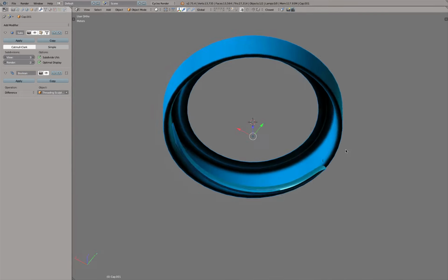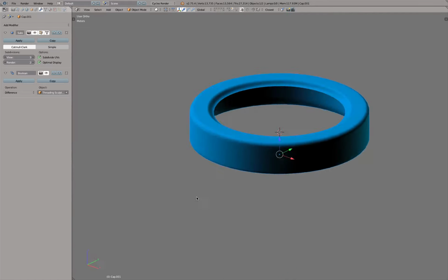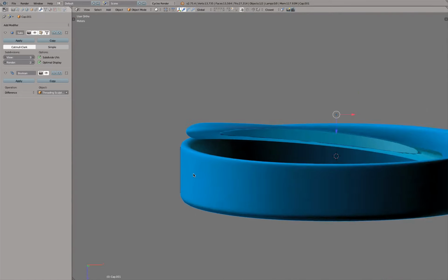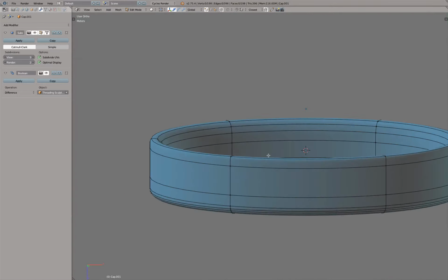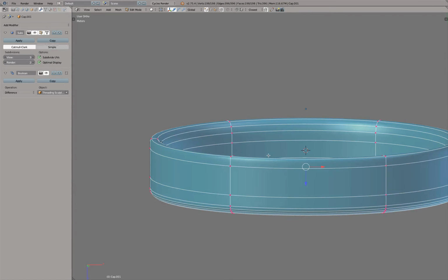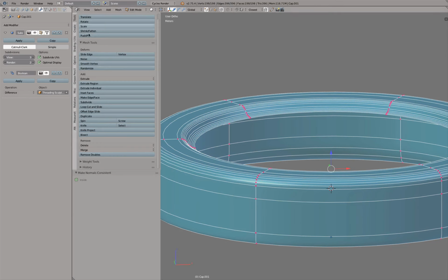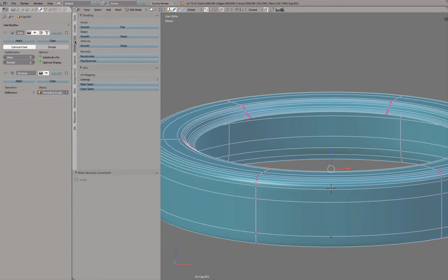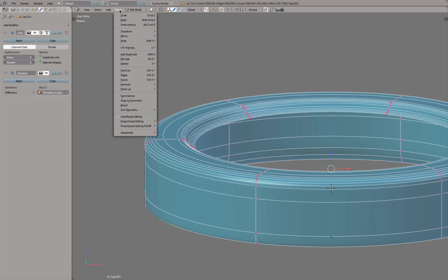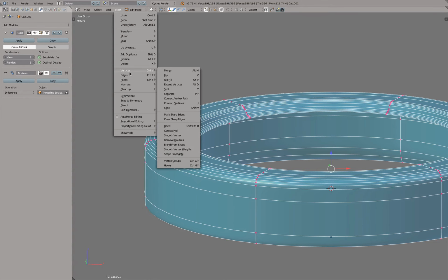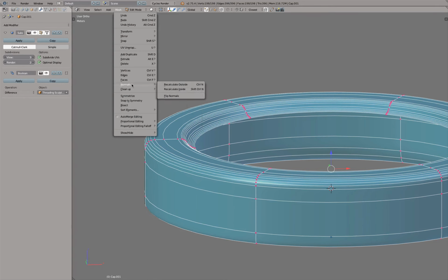Let's take a look. And what's this? This is interesting. Let's see if maybe we have somewhere some issues. Control N actually flipped and recalculated all the surface normals. So recalculate. This is also Control N. By the way, you also find all these commands, for example, normals, there, exactly the same.